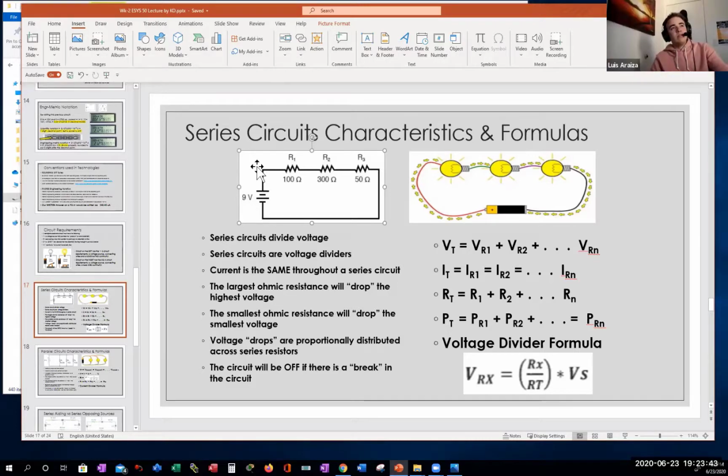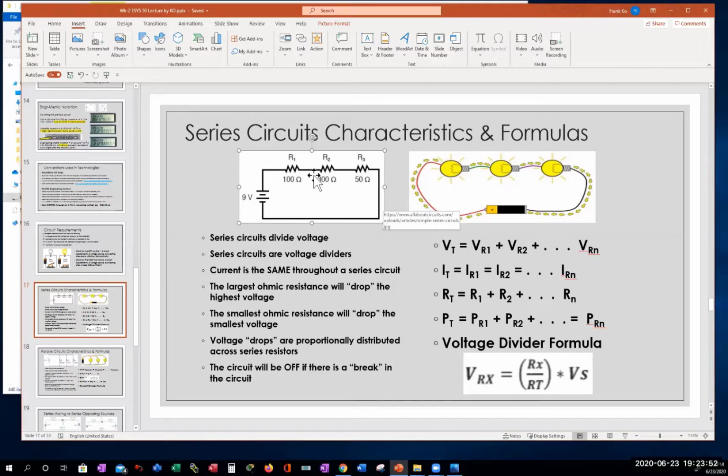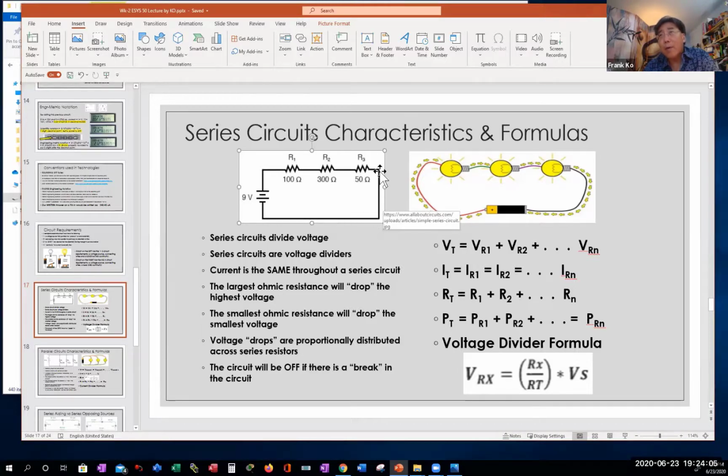Counterclockwise. Negative to positive. On the left-hand circuit, electron current leaves what plate of the voltage source? The negative. Electron current leaves the negative plate, so electrons will flow down, then to the right, then up, then to the left through the resistors to the positive side of the source. As it flows in this direction, that is called counterclockwise, and we would abbreviate that as CCW, okay?